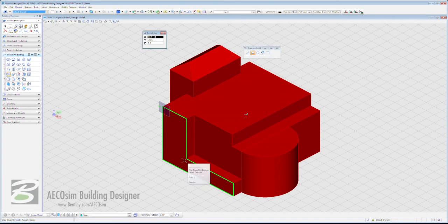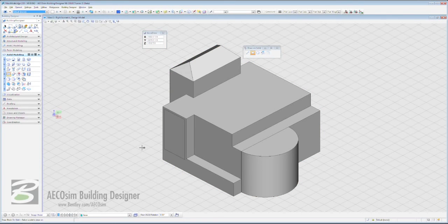And we can use this either dynamically, or we can use AccuDraw again to offset and impress upon this. But we'll come down here, we'll say O, we'll say 2, 2. And now we have this square, which then we can come back to Modify Solid Entity, select the face, and just literally use AccuDraw to depress this to a value of 2 feet, and then click once to accept and right click to reset, and again you're seeing some of the very simple power coming through.